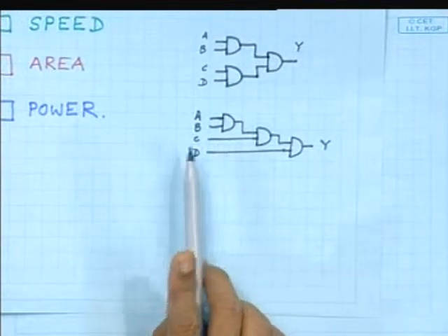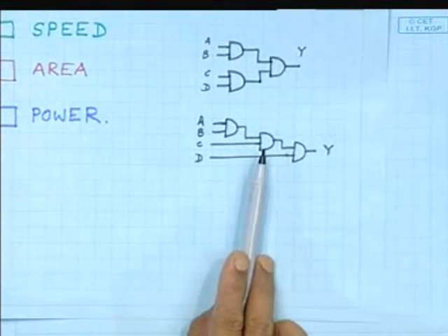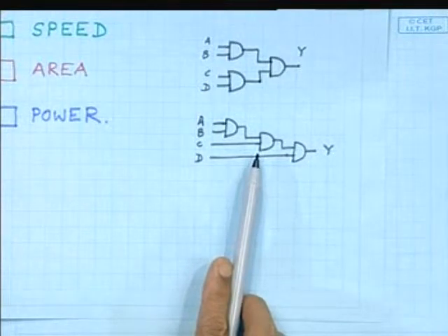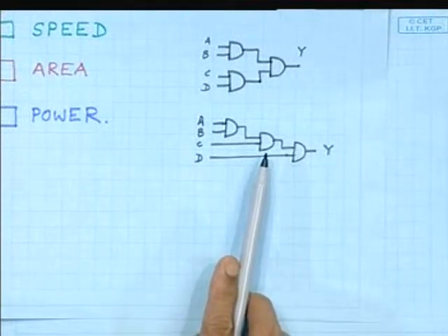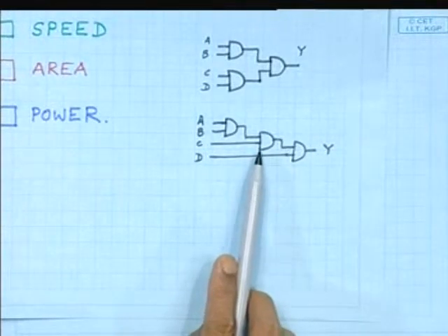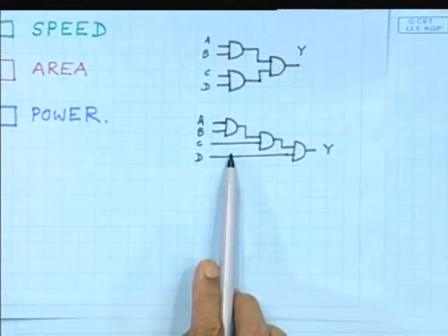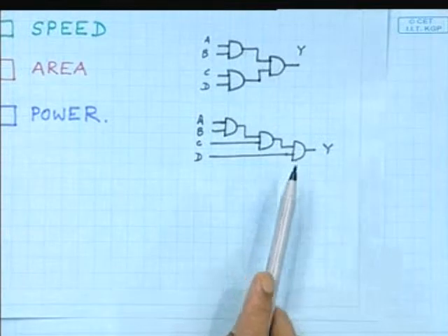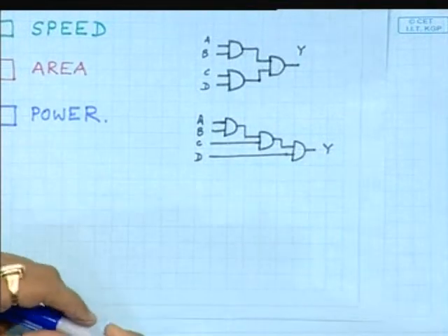That is the first observation. But still, if I say that you use this design, possibly something is pinching you, that this design is really not efficient. Maybe if you redesign your critical path and it falls below 0.3 nanosecond, then this one will become the critical path, right? But this one really has a little advantage.